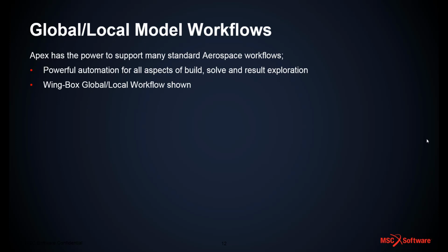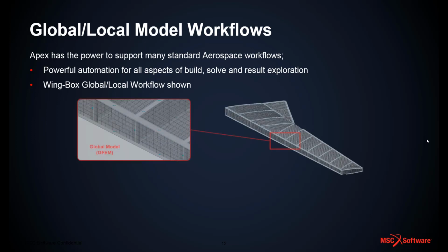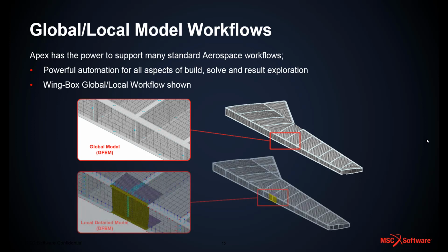We're going to look at one process which is prevalent through many airframe developers, the wingbox global-local paradigm, whereby we would have a global model, or GFEM, global FEM definition for the full structure, a wing in this case, and then we might wish to develop a local detailed model, DFEM, to tie into that GFEM to understand local response for the newly modified or more refined region. Obviously this is a fairly crude example, but is illustrative of that approach.